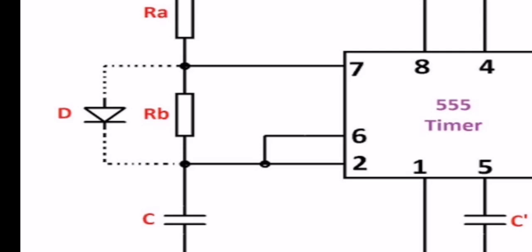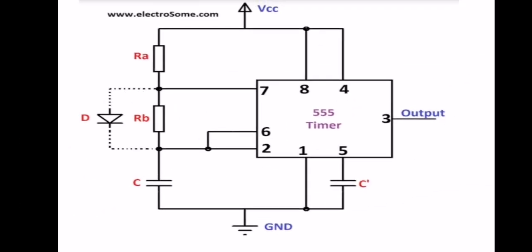As you can see initially, when we press the on switch, the output of the lower comparator will be high and the output of the higher comparator will be low. Then there comes a stage where the output of the lower comparator becomes low and the output of the higher comparator becomes high. And after going through a rectangular wave, it again comes back to the starting, where the output of the lower comparator becomes high and the higher comparator becomes low. So by using this, I have explained the block diagram of the Astable Multivibrator.